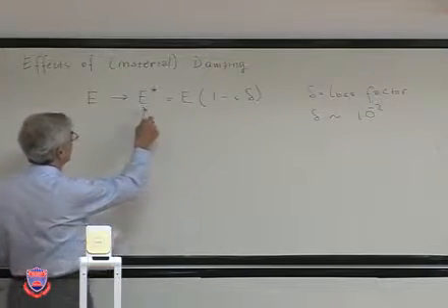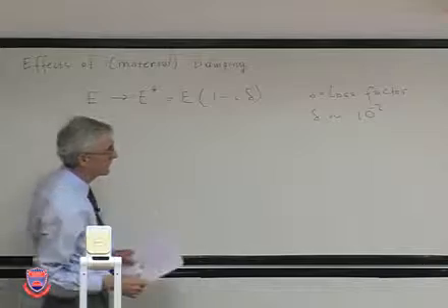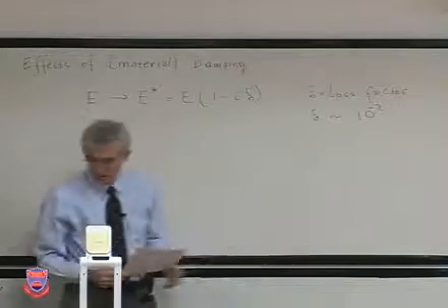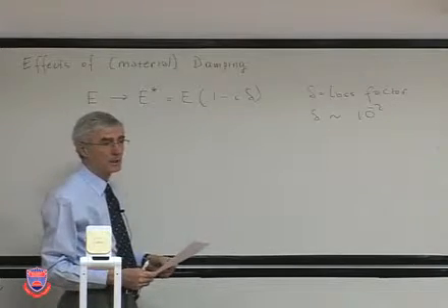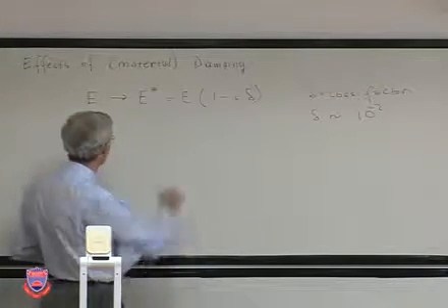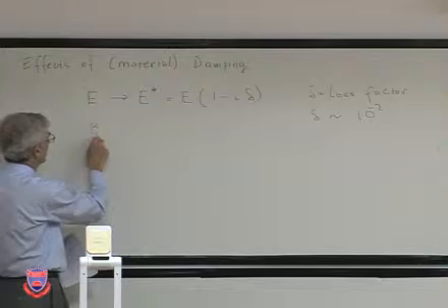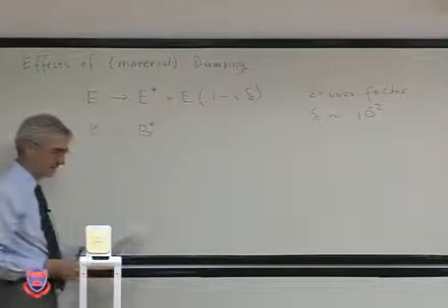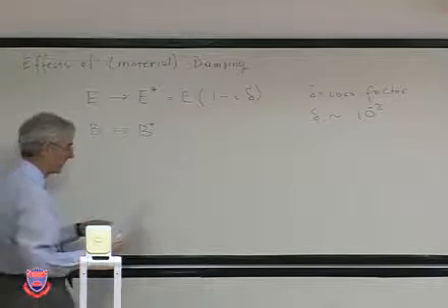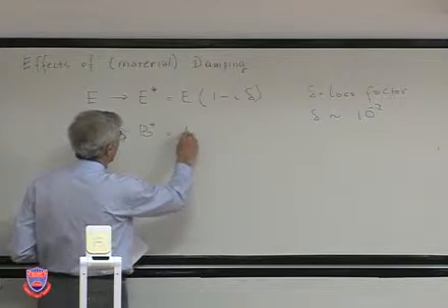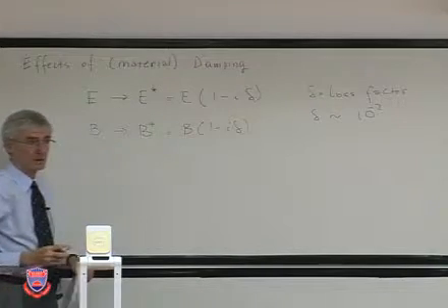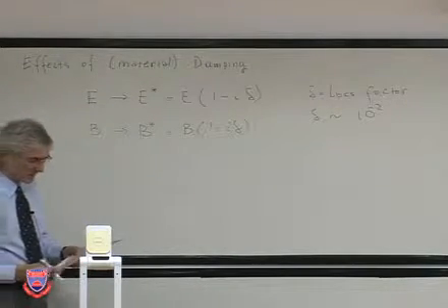Now, if we start with the Young's modulus, where does Young's modulus appear in our equations? In the bending modulus. So that means the bending modulus becomes a complex value. And in fact, we can say that because it's directly proportional to Young's modulus.